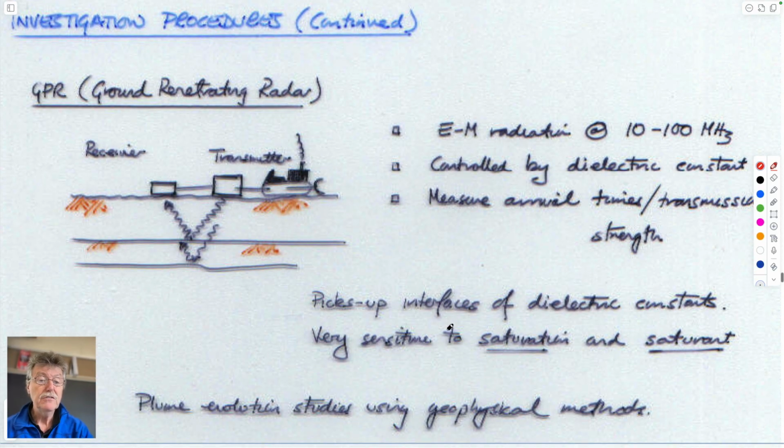The other method that's used is the same as you'd see on these archaeology shows, like Time Team, using GPR, ground penetrating radar. So the idea is you have a transmitter. They're usually a single unit these days, not two units that are separated. But you move on the surface, there's a radar wave that comes out of a transmitter, and in the same unit it picks up the reflected wave. Again, a two-way travel time as it goes across here gives you the depth of these layers.